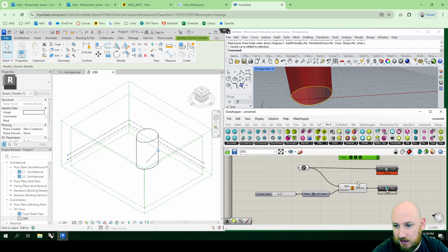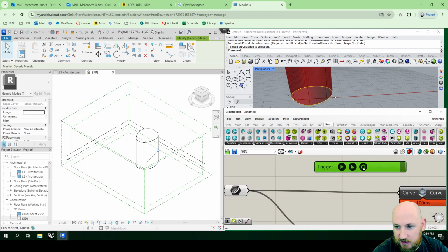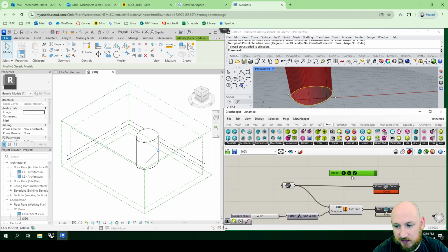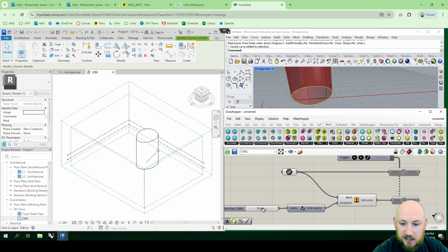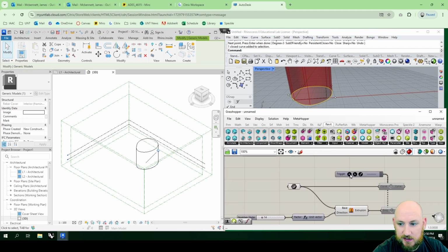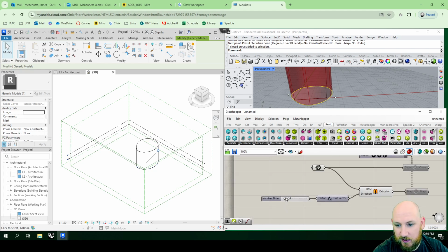To set up a trigger, you need to first lock it, so it's going to lock to whatever objects it connects to. And I could do this. This is just disabling it so that it's not going to do a live link to send information. That means now if I change this information, it's no longer sending it to Revit until I press play again. And whatever the settings are when I press play, that's the thing.